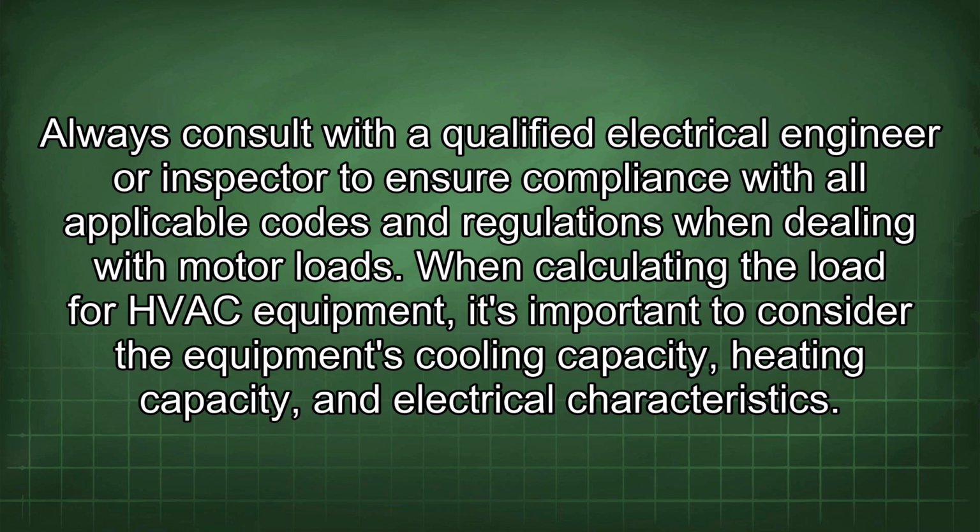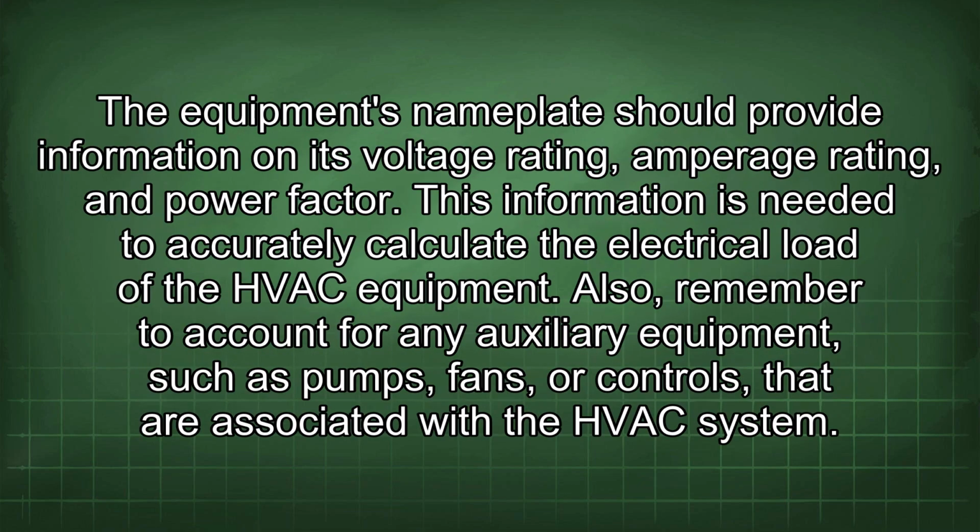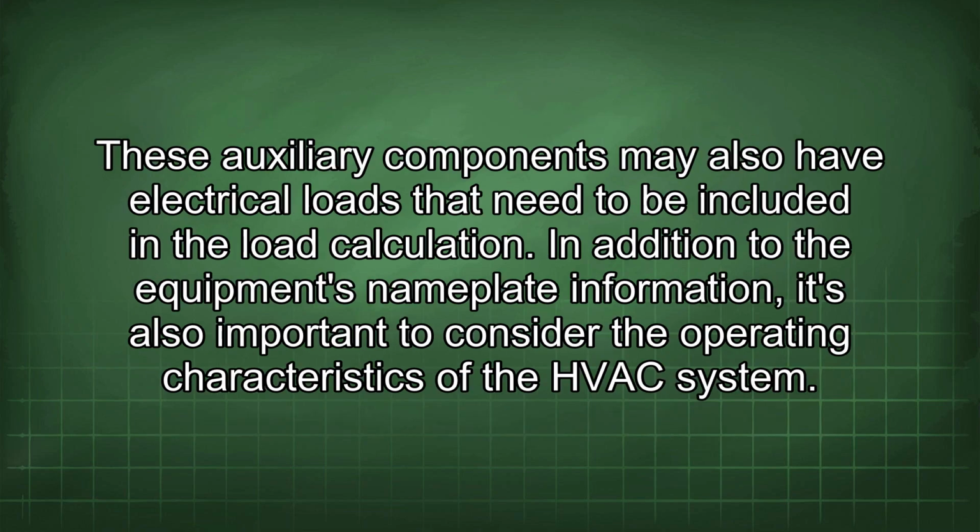and electrical characteristics. The equipment's nameplate should provide information on its voltage rating, amperage rating, and power factor. This information is needed to accurately calculate the electrical load of the HVAC equipment. Also, remember to account for any auxiliary equipment, such as pumps, fans, or controls, that are associated with the HVAC system. These auxiliary components may also have electrical loads that need to be included in the load calculation.